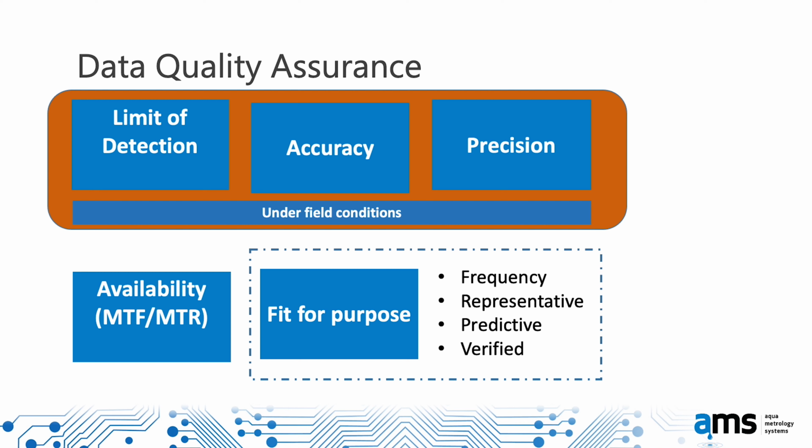Representativeness addresses a tendency by the water industry to use proxy indicators. But we all know that water is a complex chemical, and measuring the presence of a proxy indicator X for the presence of contaminant Y, because that's a cheap and easy thing to do, risks yielding false positives or false negatives. And this is clearly a false economy when Y can be measured directly, accurately and precisely by online instrumentation.